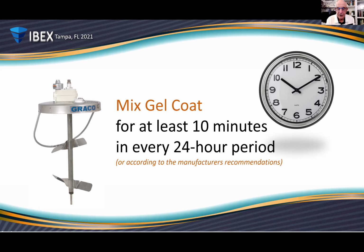But if I'm going to spray it at 5 o'clock tomorrow, I need to mix it again. 24-hour period. Or see the little caveat down bottom, or according to the manufacturer's recommendations. There are certain gel coats that the mixing recommendations might be something different than 10 minutes in a 24-hour period. Clear gel coat or a metal flake gel coat or something to that effect. So whatever the manufacturer says, they will have some specific recommendations on how to mix their material.